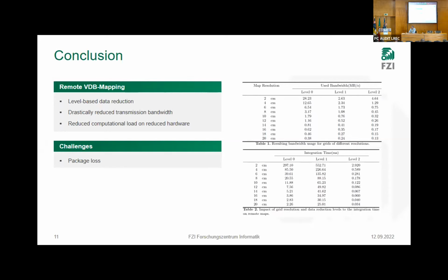In our cases, we mostly use a resolution of 0.5 centimeters for the map, which is mostly due to running navigation on it, because this takes more time the higher the resolution is. So basically, about 1 centimeter, we tested it in the initial paper about the mapping. If you go below 1 centimeter with a standard Velodyne or something, the integration process takes quite a bit of time, like a second for a new sensor measurement, which isn't real-time capable anymore, since we want to integrate the data quite fast to avoid upcoming obstacles.